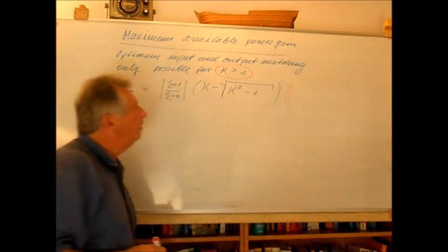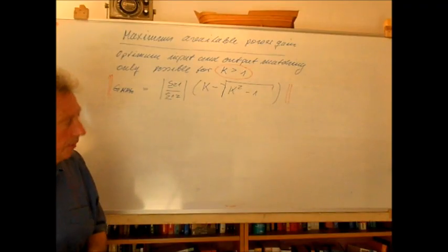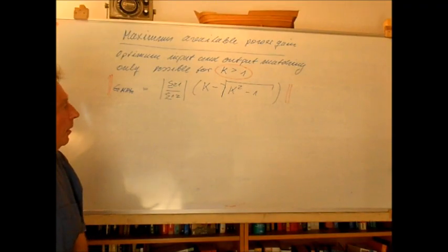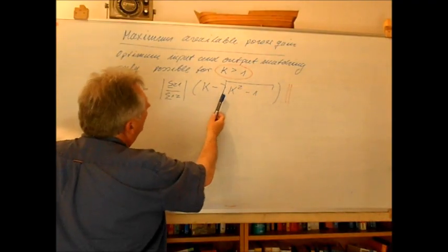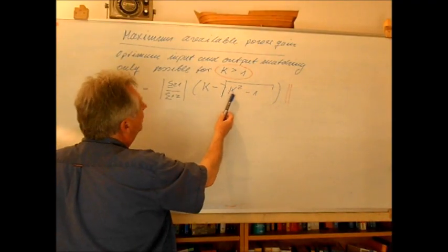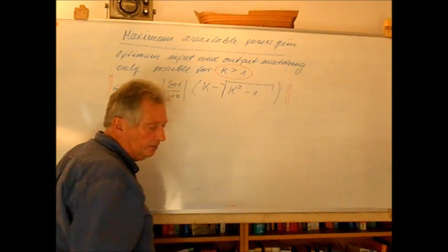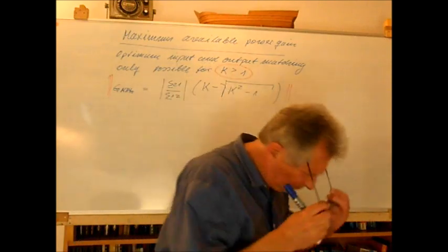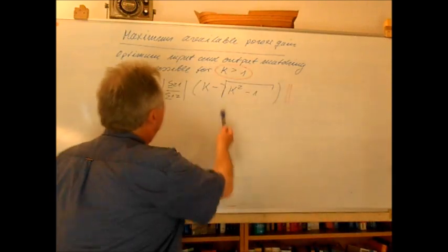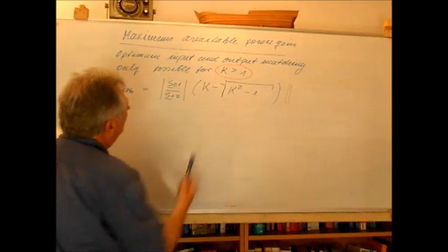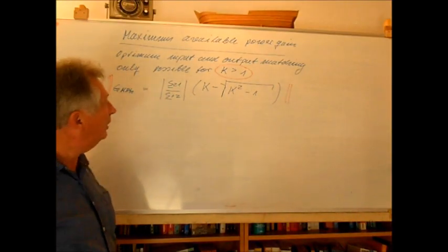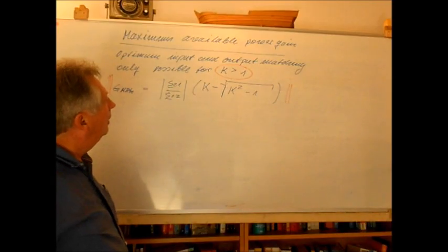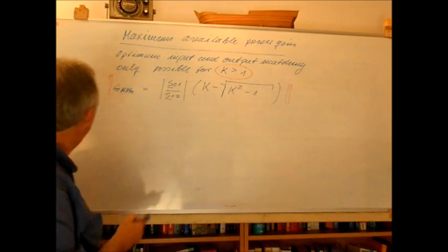But as we saw before, if I have a transistor which is not stable, as soon as K becomes smaller than 1, then this expression is not meaningful anymore, because a power gain can only be a real number.